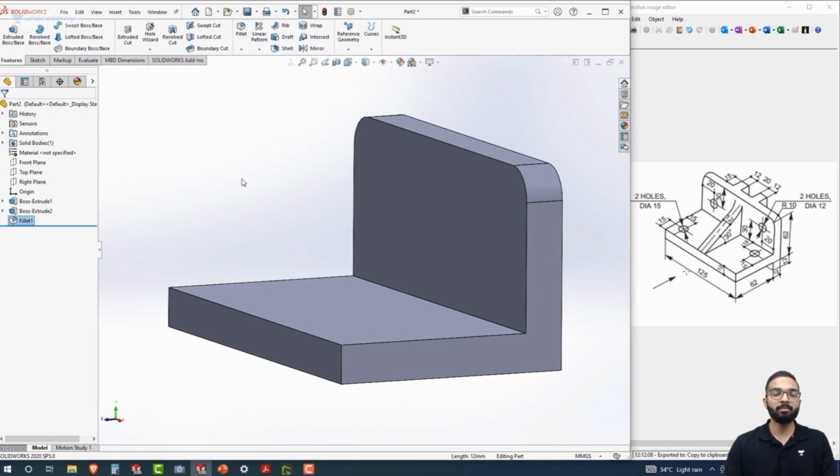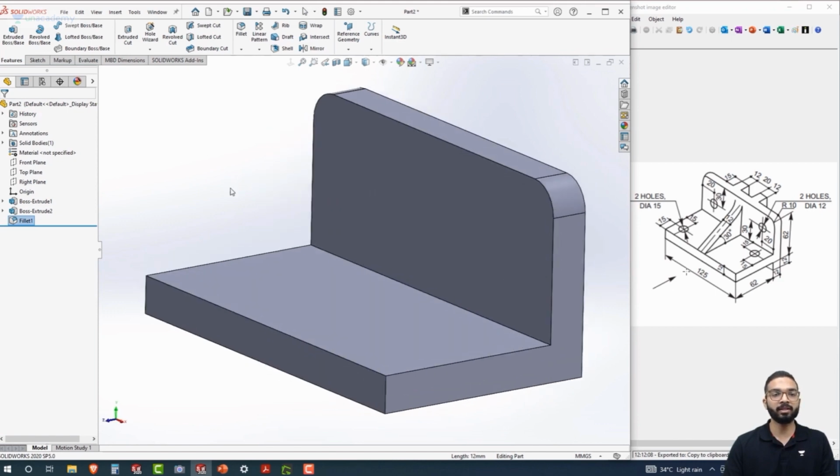But before that, as we see here, we know that our planes are not in the center of the sketch or the geometry. Now, if you want to change your geometry at this point in our modeling, you can do it very easily. I will show you how to get this plane at the center of the geometry. First, we will roll back our features till the first one.